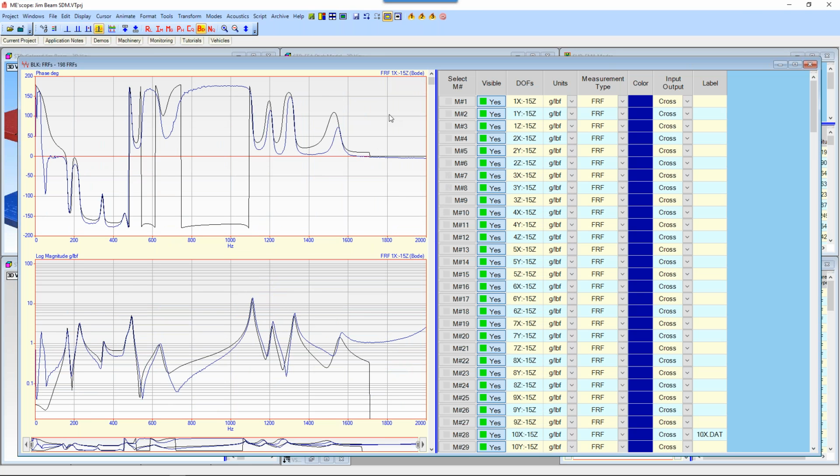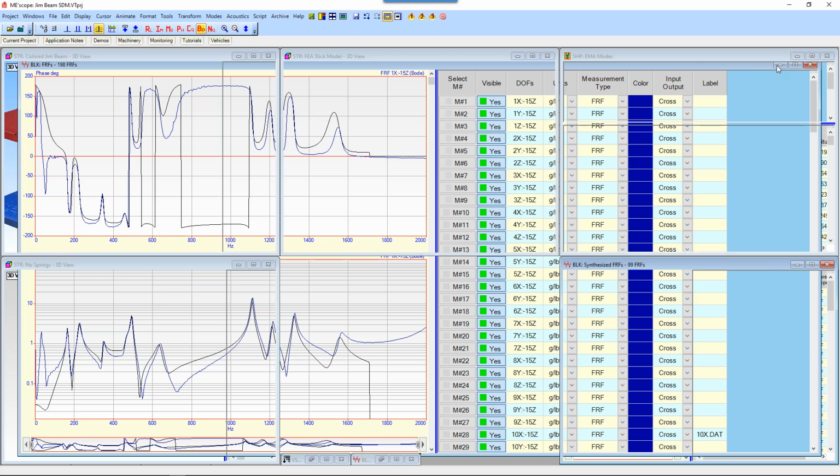We can go ahead and use this modal model now and do some SDM, or we could go ahead and, let's say we didn't measure the driving point and we just had some residues, or we had some OMA data where we couldn't measure the forces. All we had was a curve fit of some cross spectrum or ODS FRF data. We couldn't measure a driving point. Another way to scale the data is to use FEA mode shapes. So let me do that.